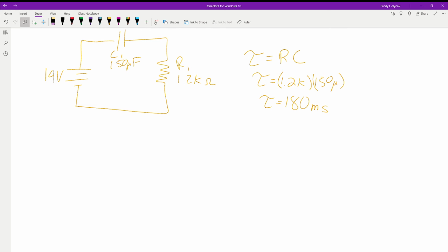Okay, so the first thing we're going to do is solve this equation. We're looking at it in reference to time. So this is where we're going to come into the logs. First thing we want to do is solve for the voltage of our capacitor at 1 tau. So we need to use our instantaneous voltage equation to solve for this value.